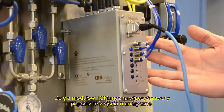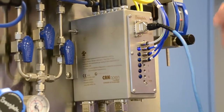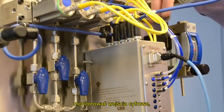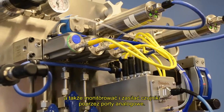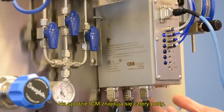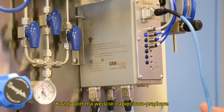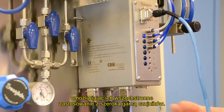So with an ICM, you can actuate valves with its pneumatic outputs, you can monitor digital inputs with its digital inputs, and you can monitor and power your sensors with its analog ports. There are 4 ports on the bottom of the ICM. Each port has both voltage inputs and a current input that make it versatile for use with a wide variety of sensors.